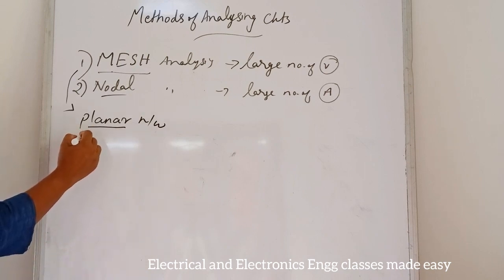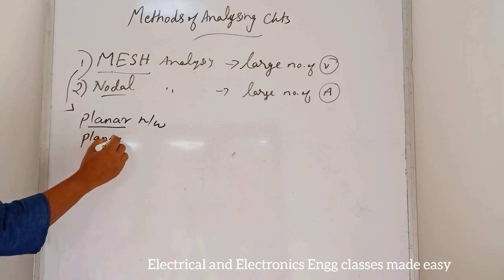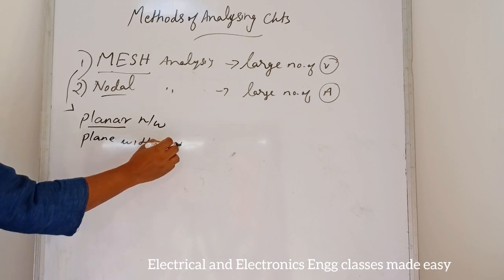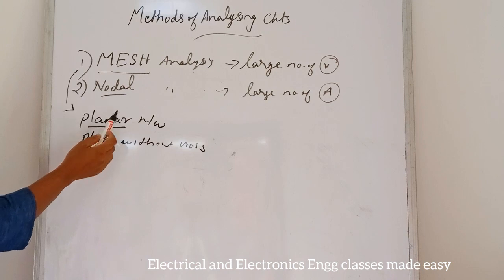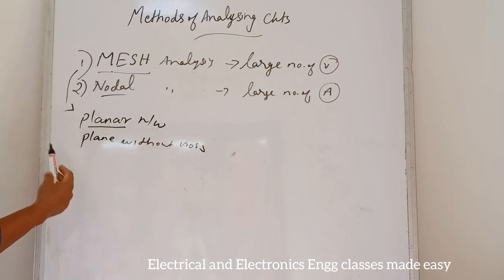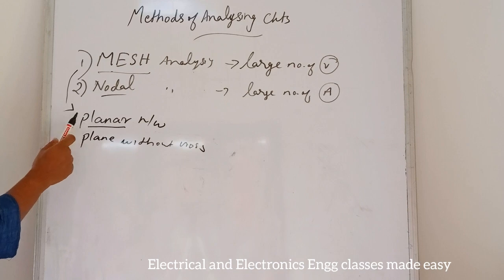So planar circuit means it can be drawn on a plane surface without crossovers, and a non-planar circuit cannot be drawn on a plane surface without a crossover. So, mesh analysis is applicable only for the planar networks.